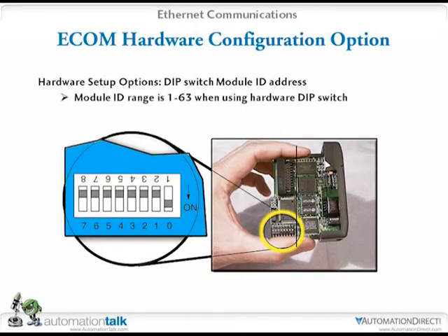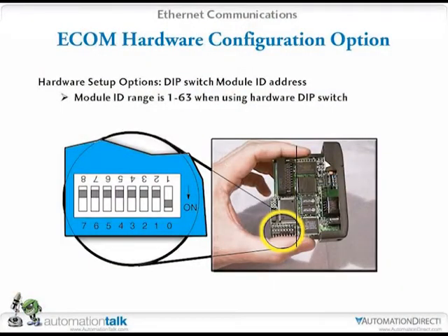Configuration options, you've got a couple of different ways: IPX, TCP/IP, all kinds of stuff. You can get heavily into the Ethernet communications protocols, but you've got dip switches you can set up, and you can give these names. It's been a while since I've set up one of these. I'm used to setting them up with NetEdit within the software, but I remember you can either set it up in software, or as this slide shows, you can set the address, which would be the node address, with a dip switch. Don't ask me what; I have to break out pen and paper to figure those out.